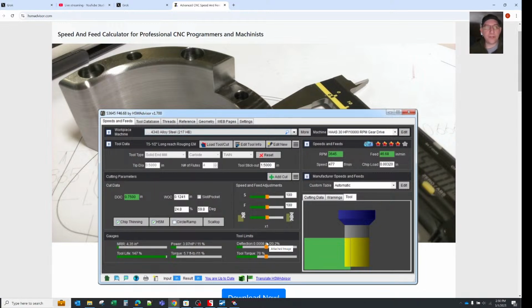So then that allowed me to go, well, maybe I should try a 3/8, and maybe instead of a 500 thou depth of cut, I backed it off to 300. And then you could adjust the slidey bars here or type in numbers and go, okay, well, give me 70% of the recommended. And the other way that I use that is when I'm designing fixturing.